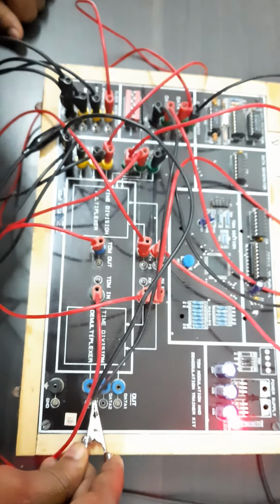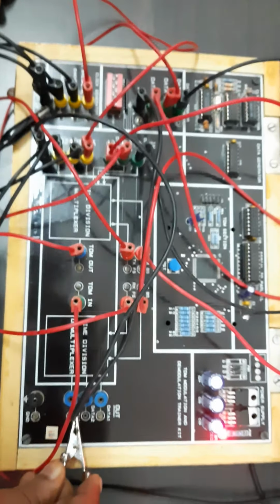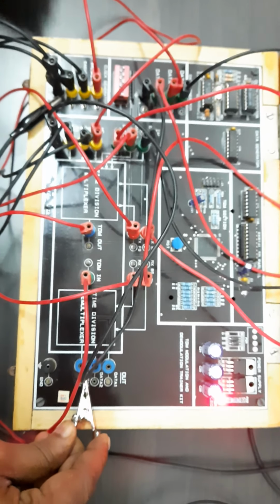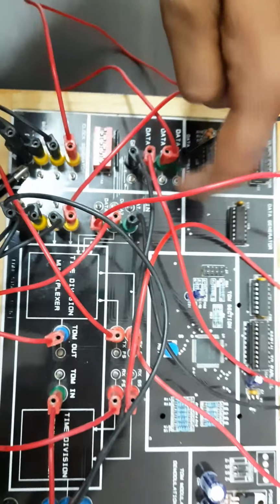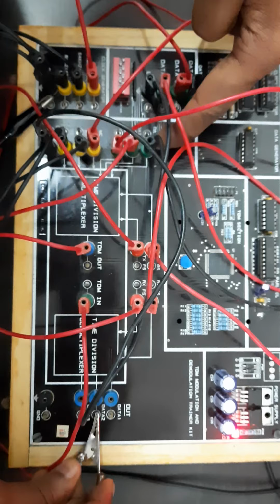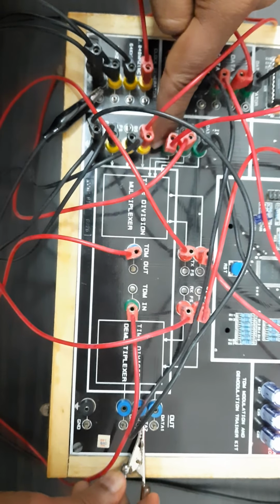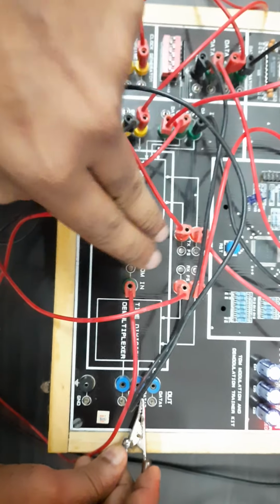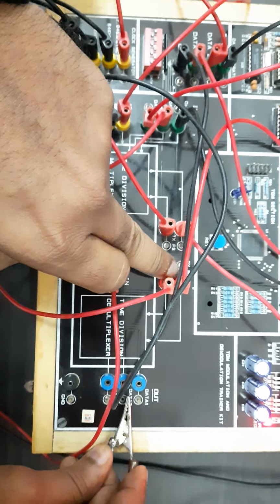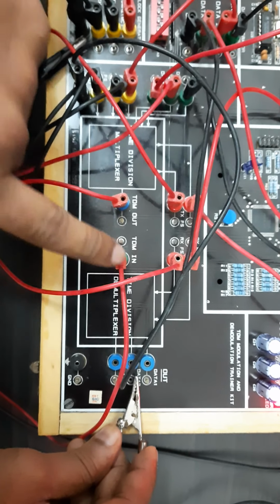Details of the theory of this will be given again in the form of text. This is how the experiment is conducted. It's very easy. I'll summarize in one minute how to do the connections. First you make the connections of these three green color knobs, that is data inputs to the TDM inputs, green to green. You can vary the data pattern by using these knobs. And this is a clock generator, LO to LO, three knobs. And then here the frequency and bit synchronization of transmitter and receiver. And here we will get the TDM output. This has to be given to TDM in.